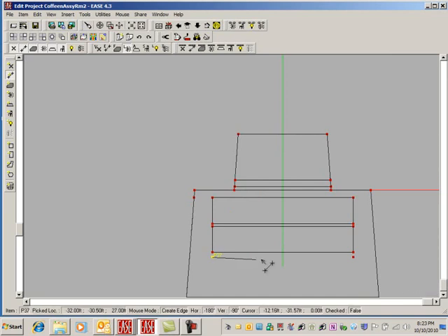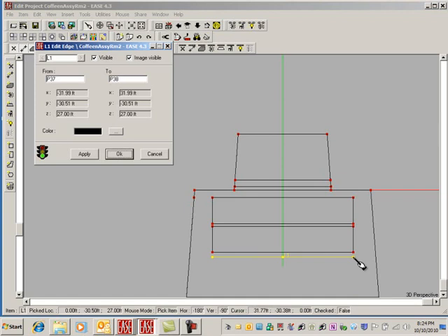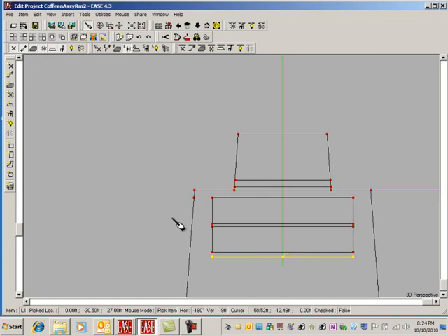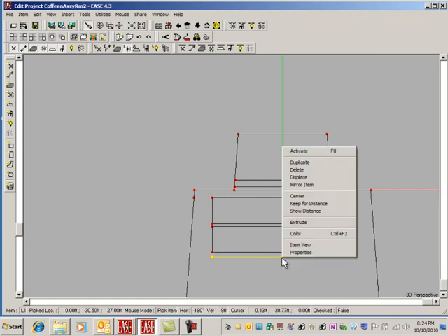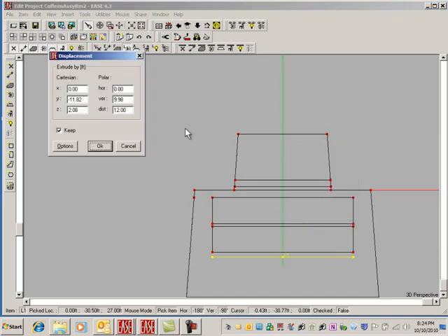Now we have another one which is down 1 foot and 15 feet back farther in the room. So if we just say duplicate this guy, minus 15 feet this time, and Z minus 1 foot because it's now down 1 foot farther according to the dimensions on the section. Minus 1. Okay. And all the materials are okay.